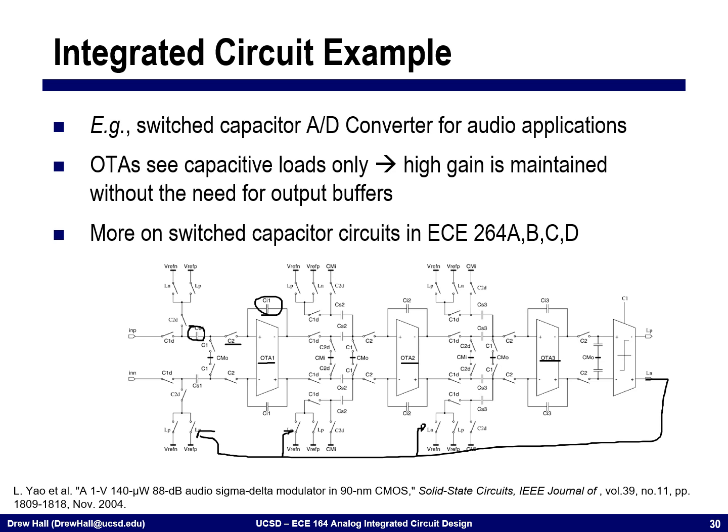The important part here is that the OTAs only ever see high impedance loads. And so we don't have any output resistance or small resistance that loads this output stage. So these switched capacitor circuits are something that you will talk about extensively in 264. They're essentially the way that all integrated circuits are designed.